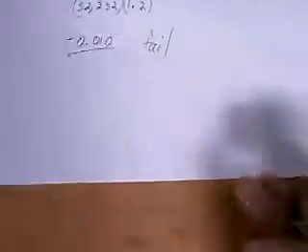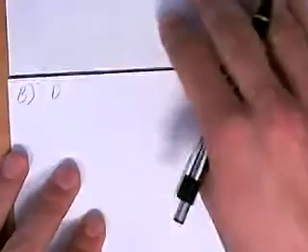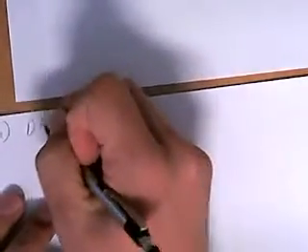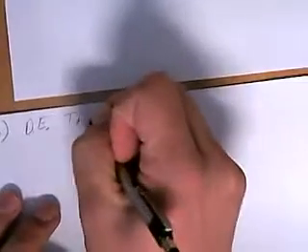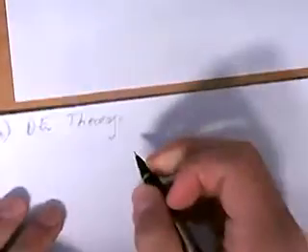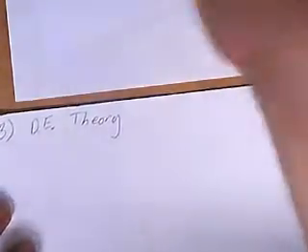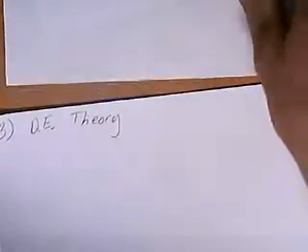So now, moving on to distortion energy theory, part B. If we do it with distortion energy theory, you first have to find the von Mises stress, so DE theory. And in order to find von Mises stress, you're able to use the original stresses that we calculated clear back at the beginning of the problem back here, so sigma x and tau xy.